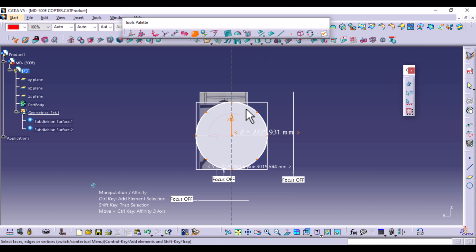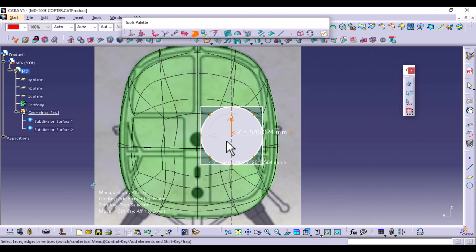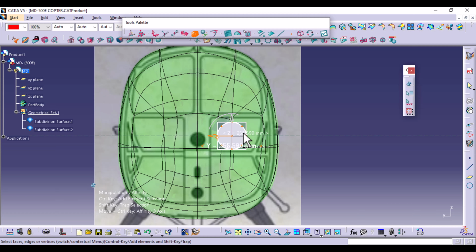One thing to mention is that the size of the mesh is kind of related to the size of your screen. So everybody can get a different sort of mesh based on your screen. But there is, I think, a quarter of your screen size. But there's no problem because you're just going to drop it down to whatever size you want. So we're going to reduce this like so, and then click apply. So kindly note that when you want to move both vertical and horizontal directions, you just go in the middle, because if you move one, then you're going to lose the circular shape. And I wanted to maintain that. It's not completely circular, but we're going to get that in a while.